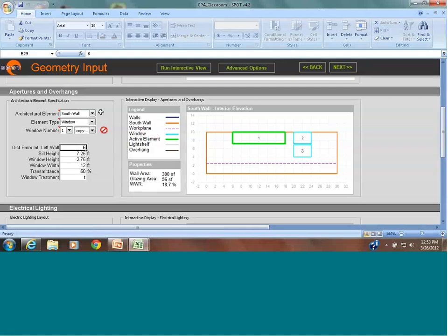Does this help with energy consumption as well as occupant comfort? Yeah, this will. So right now all we looked at was the maximum daylight autonomy and minimum daylight autonomy and the amount of light in the space. So that takes care of the visual comfort standpoint, right? I'm bringing in enough daylight and I'm bringing in quality daylight.